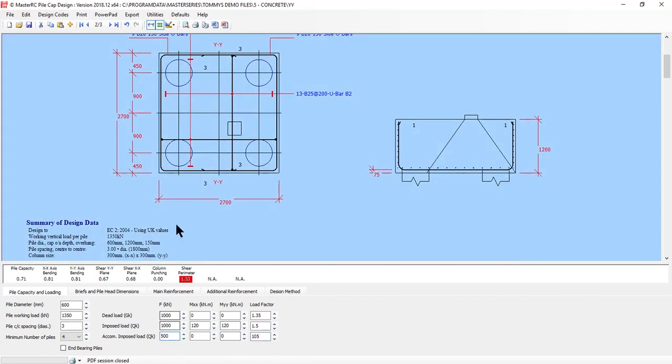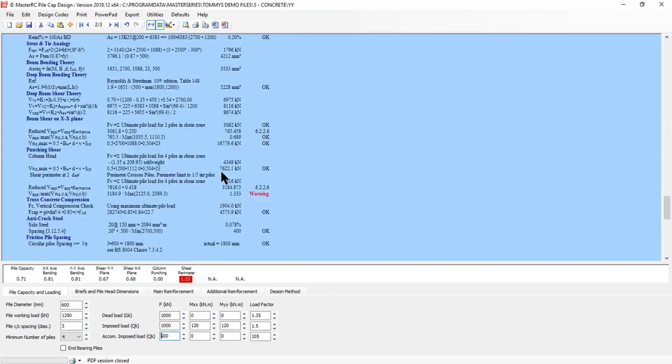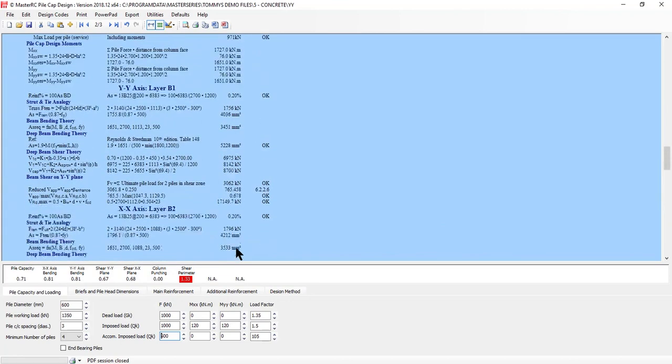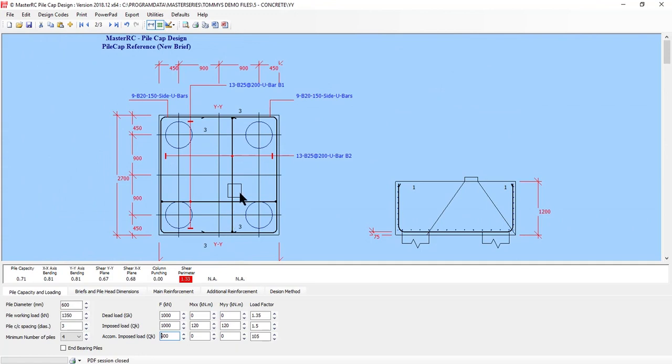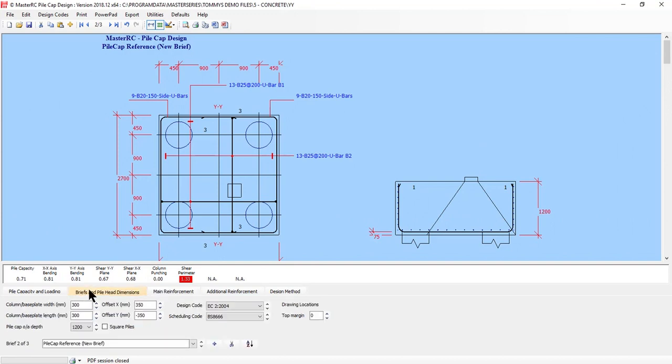So putting in a physical load, you can see now the shear perimeter is unhappy, and it's giving us a warning on our shear perimeter. Due to the enhancement, we're at 1.33, 30% overstressing in our shear. So what do we do? Very simply, we can add more rebar in the right axis, which isn't always that beneficial, or we make the foundation deeper.